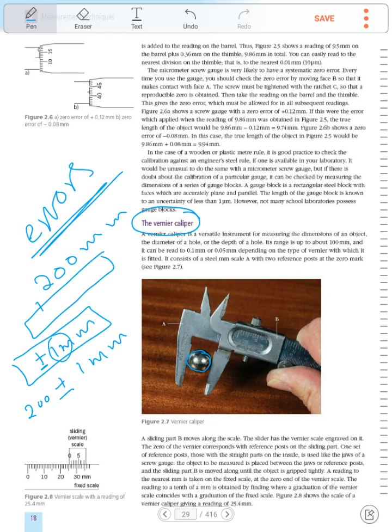Why 1 millimeter? Because you have an error from both sides, error from the left side and error from the right side. Each one is half the smallest division, so the total error, half smallest and half smallest, is the smallest value in the ruler, which is 1 millimeter.